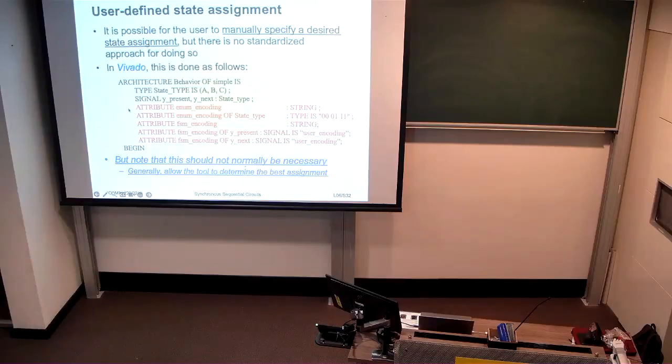Might not be obvious. It's using more flip-flops, 3 rather than 2. That's not a huge difference, particularly when you have thousands of flip-flops on the FPGA. So that's one reason why it doesn't come with a high cost. But the benefit, you were going to say something?